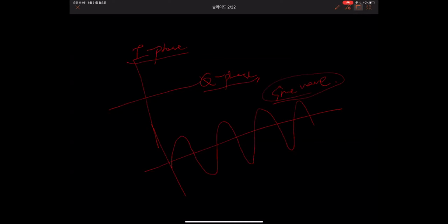If I want to say 1010, then I can say this is 1 and this is 0, so I'm changing the Q phase. 1 0 1 0. Therefore, your signal looks like this, and the receiver may receive something similar, meaning this is close to the 1 pattern that I'm expecting, and this is close to the 0 pattern that I'm expecting.